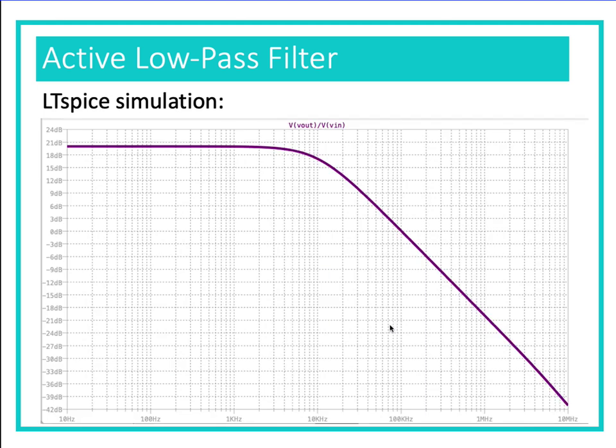And when we do that, we get this output. You'll notice that the low frequency gain is 20 dB, which it should be. And then if we go 3 dB below that, to where the trace intersects the arrow, and then drop down, we get our break frequency, which is 10 kilohertz.